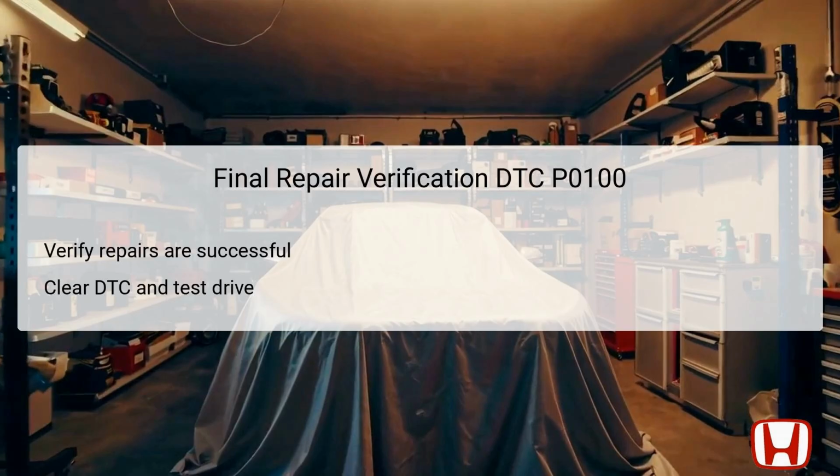After completing all the necessary repairs for DTC P0100, it is essential to perform a final verification. Begin by clearing the DTC using a diagnostic scan tool to reset the PCM. Following this, a test drive should be conducted to ensure the vehicle operates smoothly and that the error does not return.